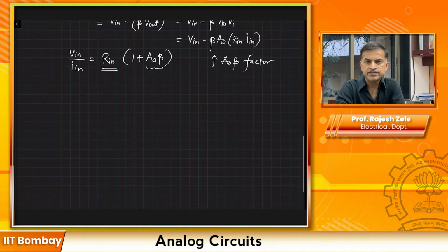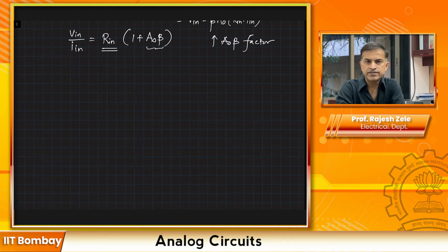And there what you would do is, I'm just going to draw the schematic for you. When you're doing the output impedance calculation, you would ground the input and then apply a test input at the output so that we can figure out how much current is going into the block. And that would be your output resistance or impedance.